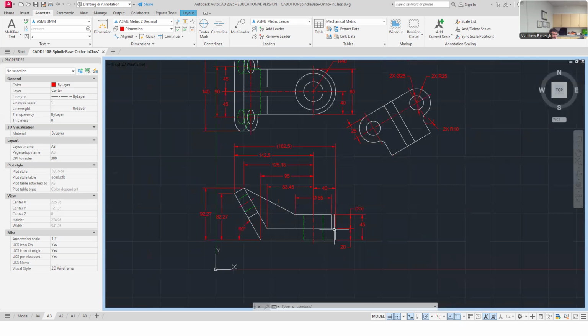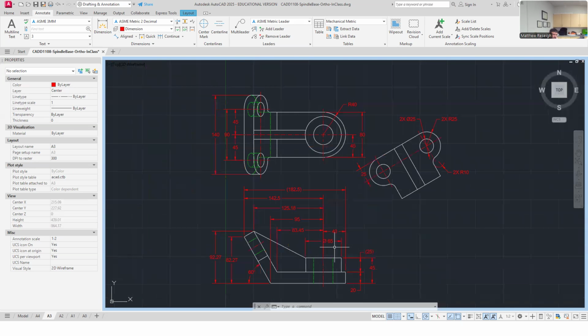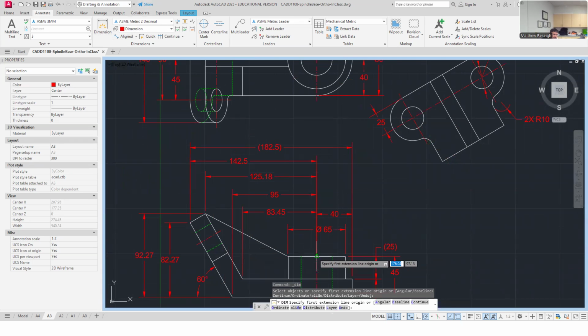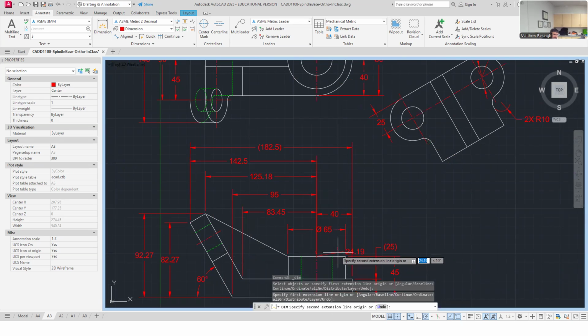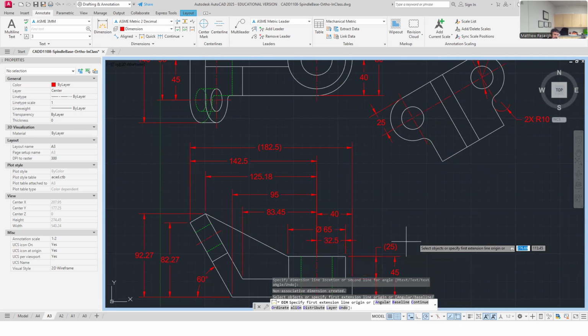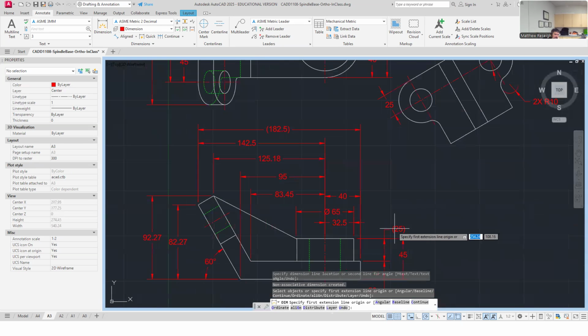Okay. And then location wise, well, that's where this weird dimension comes in here that I'm going to say, I'm going to locate it right here off this same control. That's a location off of that datum. It's this far over, and then it's a 65 diameter.